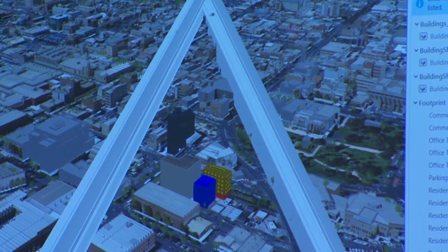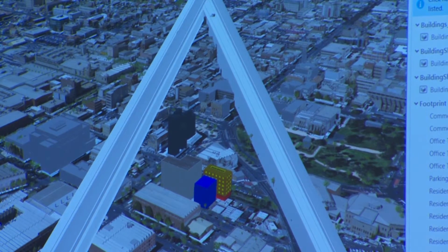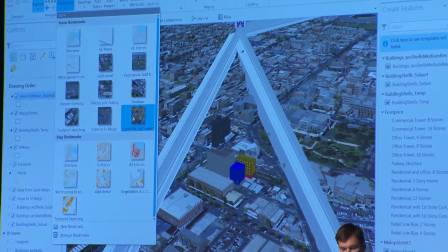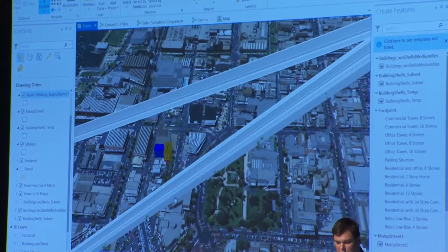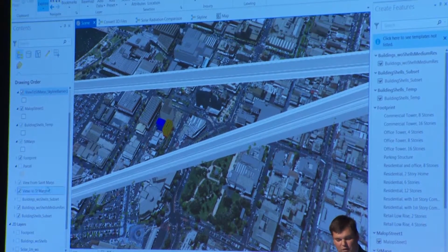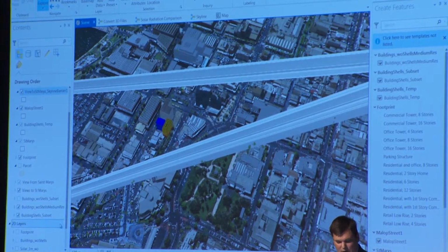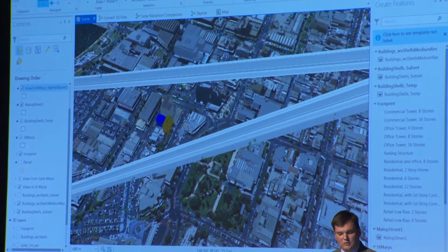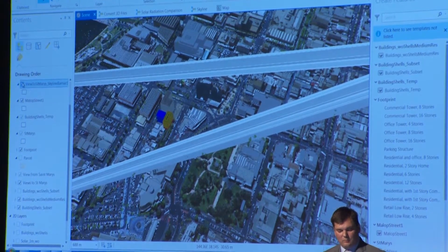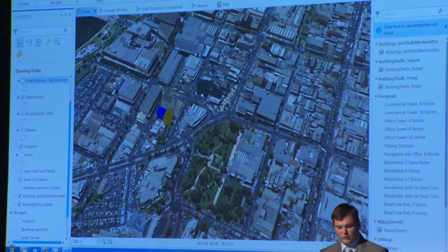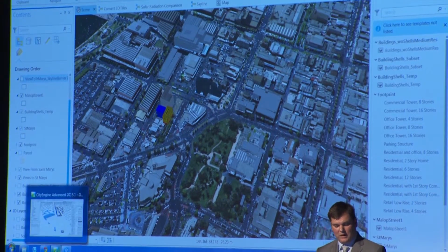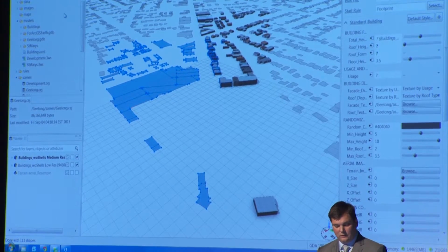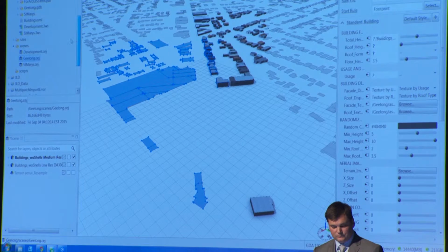So now this is a pretty rough proposed design, so I might want to continue to enhance and improve on this design. So what I can do is I can actually take it and export it to CityEngine. So do a clip and extract on the elevation and the imagery services, and then pull out all the multipatch features, and then reach back into the city's geodatabase to grab other kinds of geographic features.